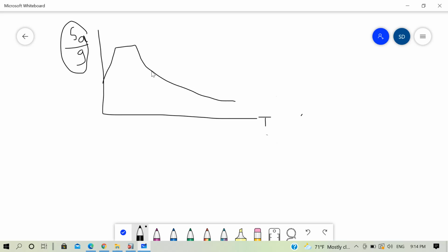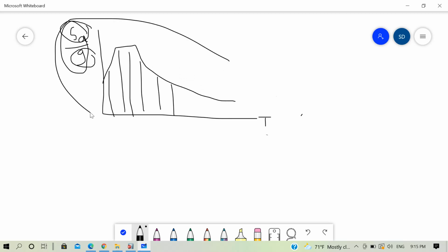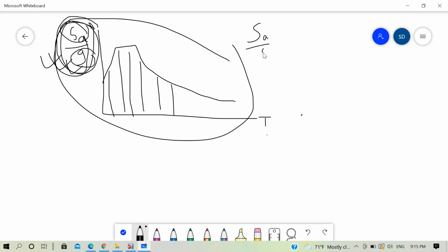So we can say that the spectrum ordinates defined within our code and also various other codes that we may look at are normalized values. These spectral ordinates, or these y-axis values, are normalized values in which our spectral acceleration is divided by gravity acceleration. You can see here the spectral acceleration is divided by gravity acceleration and we get the normalized values of y coordinate from this graph. What we should do when performing response spectrum analysis is that this spectrum must be converted to the specific set of units which we are using in our model. This value of ESA by G is the acceleration that will be applied as load to our buildings, but this acceleration value is unitless here.